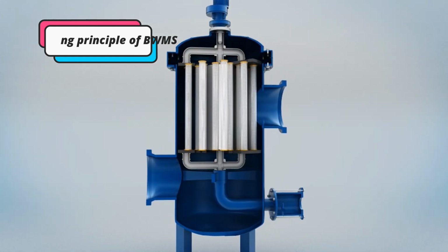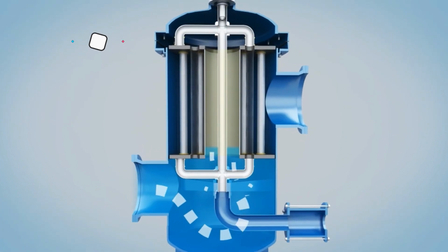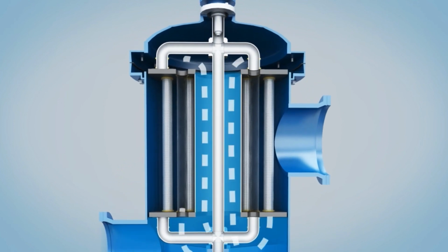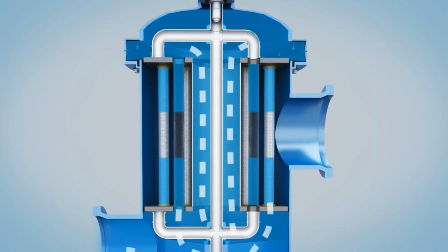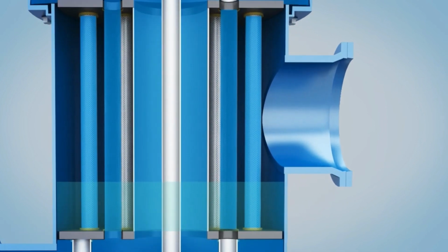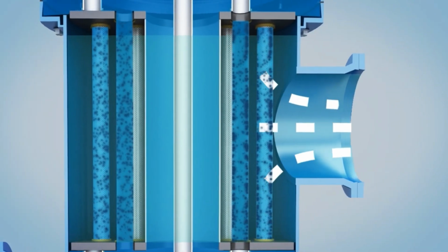During filtration, seawater flows into the filter housing via the inlet flange. Some of the unfiltered water flows into the upper section of the filter by the vertical tube between two filter mesh inserts, and reverses to the filter mesh inserts. This means that the water flows into the filter inserts from opposite directions, then organic and inorganic particles larger than 50 micrometers are separated inside the filter candle, and clean ballast water flows out through the outlet of the filter.